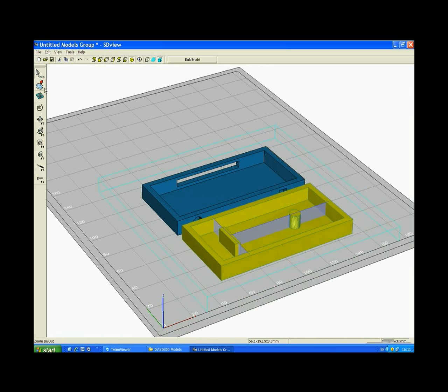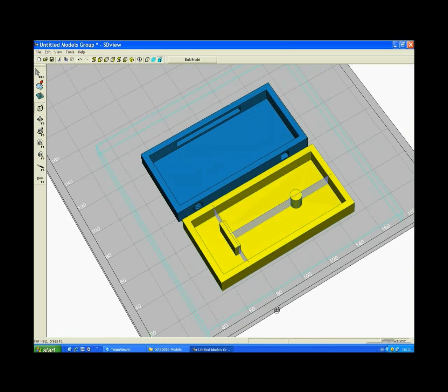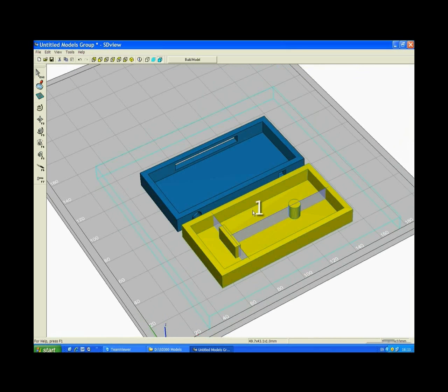You may now see the peeling cuts we placed, dividing the inner area of the part into 3 sections: 1, 2, and 3. In this way, we can peel each section without overrunning any one of the features. When peeling this section, for example, this area will provide a support structure for this post.